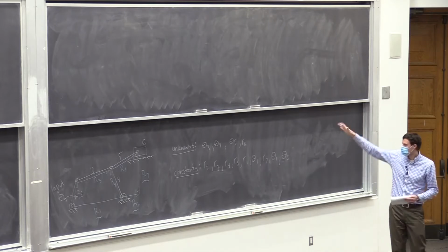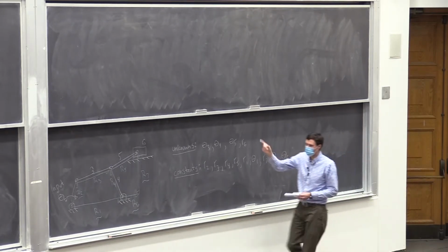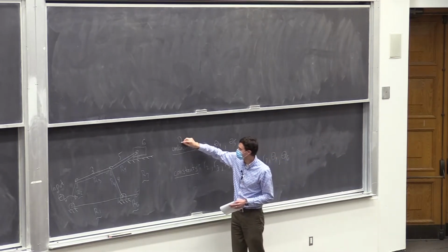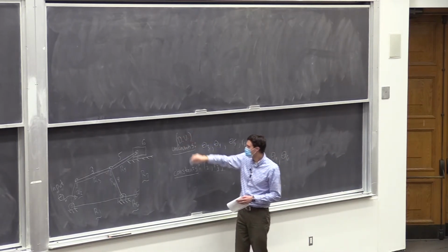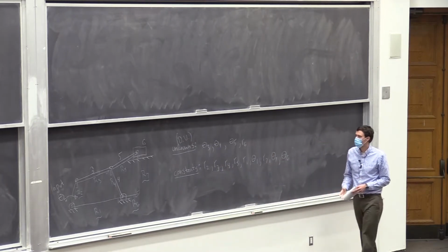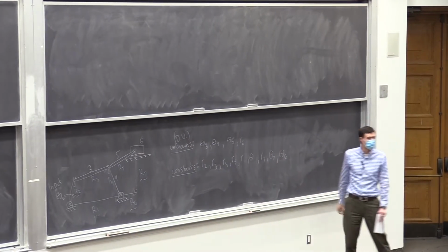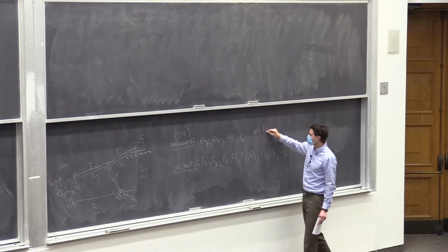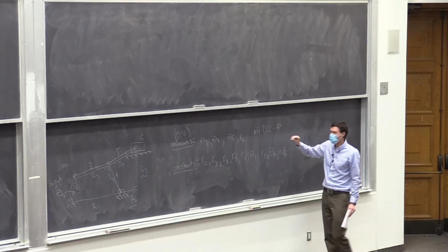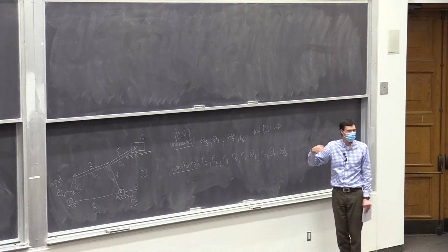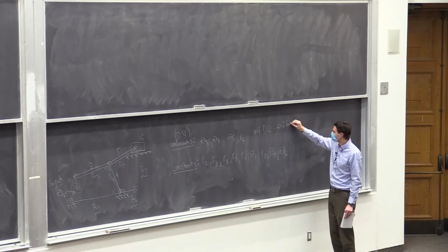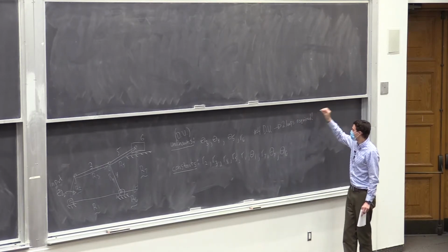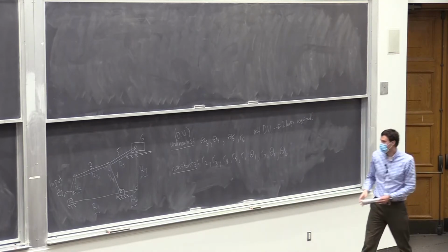So that's everything. So we've categorized all of our variables as input, theta 2. Unknowns, these are our dependent variables. And constants, which are the easy ones. Okay, so we have 4 unknowns, 4 dependent variables. So right off the bat, you should see that and say, clearly we have to have at least 2 loops. 2 loops are required to solve this. You could use 3 loops even, but at least 2 is needed.